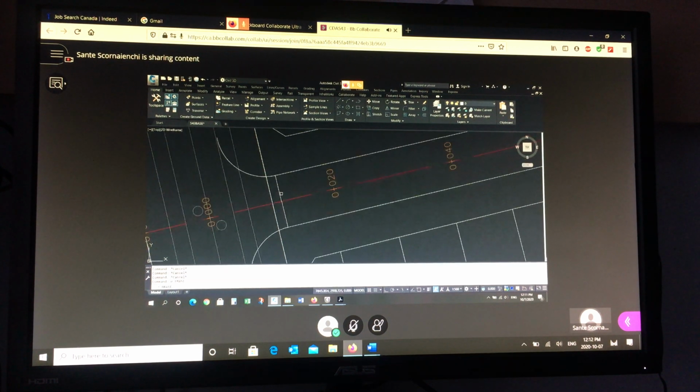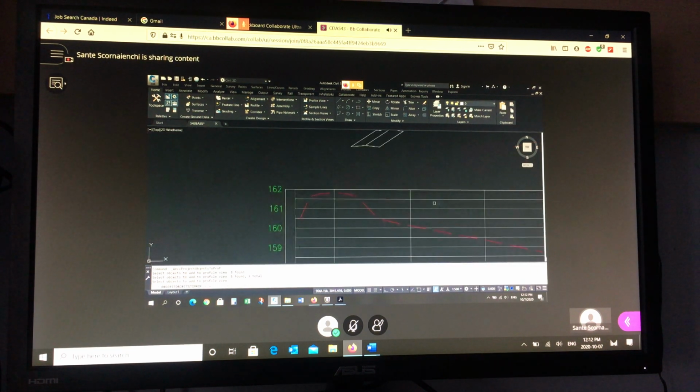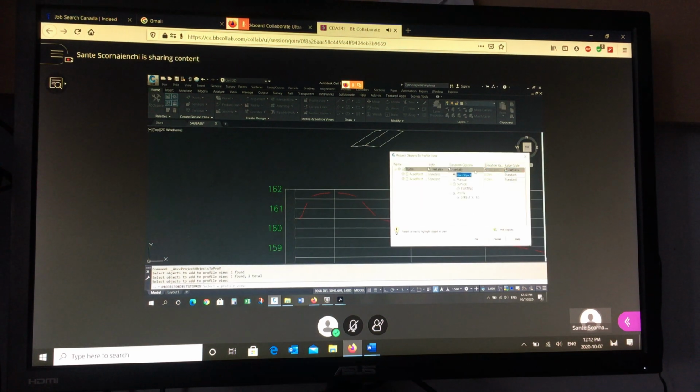Okay? Now it's hard to see if you don't draw those two lines. So what I do is I put a point in at these ends, put another point here, and I project these two. When I project these two, it'll actually figure out the station value perpendicular to center. Okay? So at a glance in plan, you can't tell which is further away from the intersection. I know it's this one. But if I put the point here and here, not on the center line, watch what happens when I project it. So I'm going to project both. Enter, I'm going to go to the grid view, somewhere near the intersection. And again, the elevation is 0, so I'm going to say temporarily put it on the existing ground, because it's really the station I'm after.